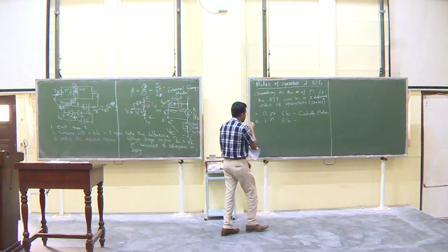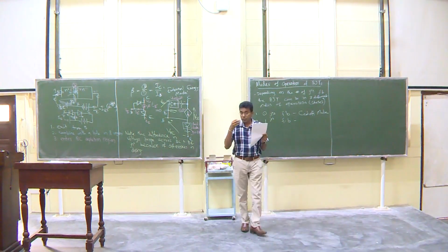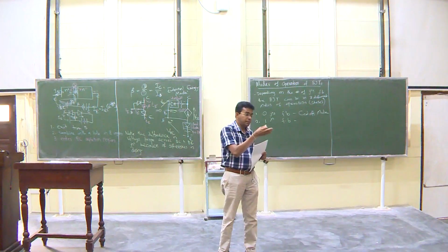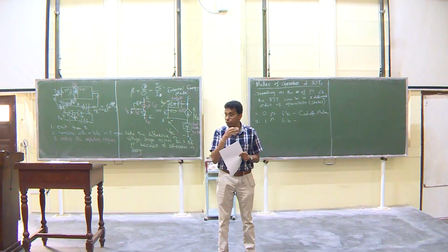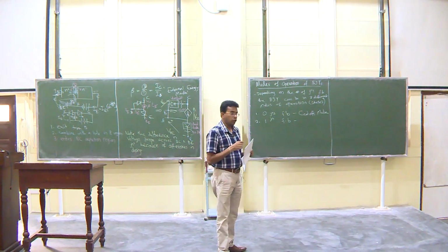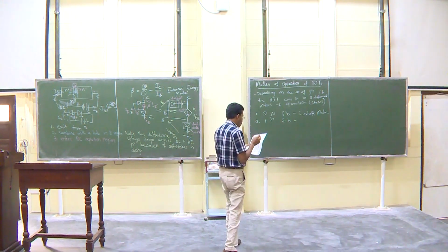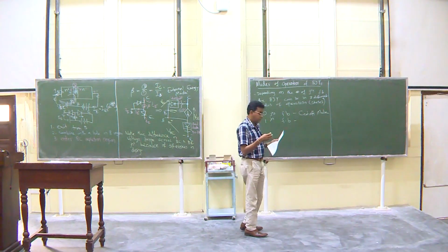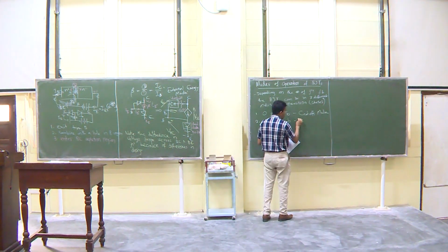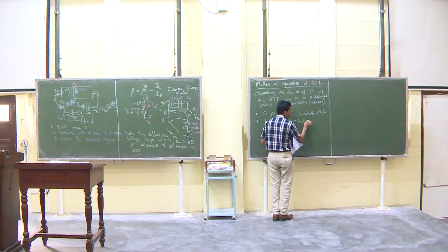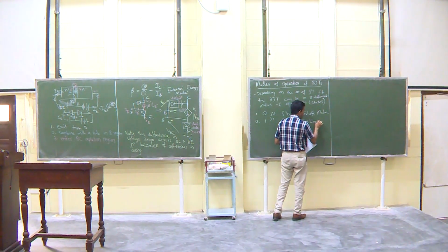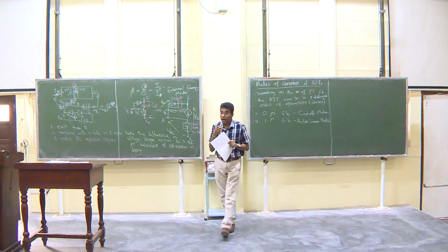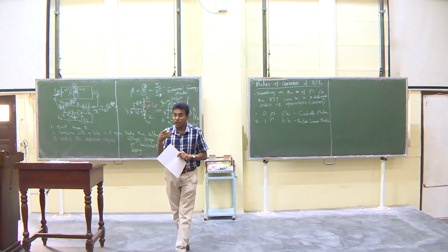What we are going to discuss is applicable even for base emitter junction reverse biased and base collector forward biased, but with much less efficiency. This is called the active linear mode, and this is the mode that we are interested in when we design amplifiers.